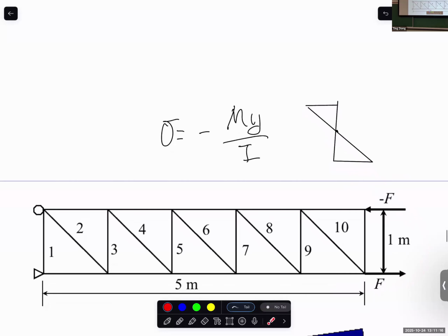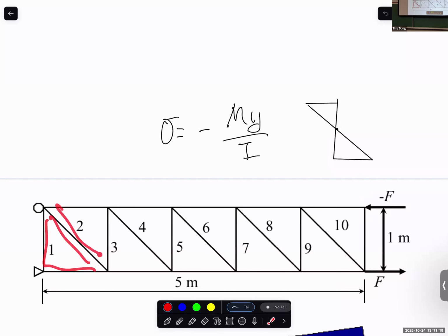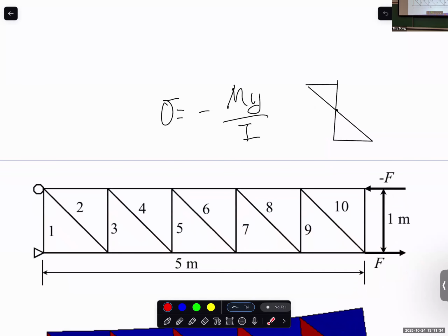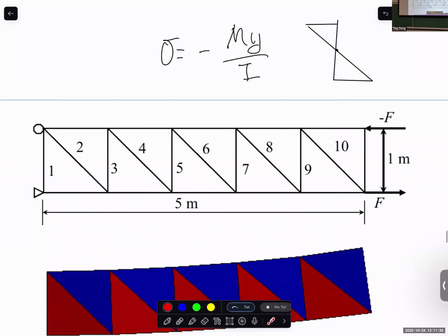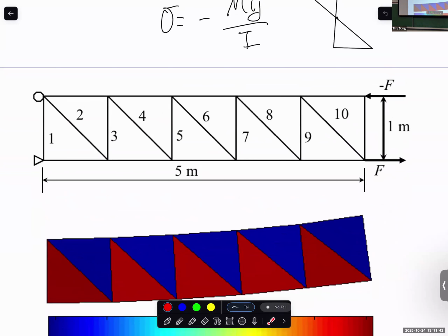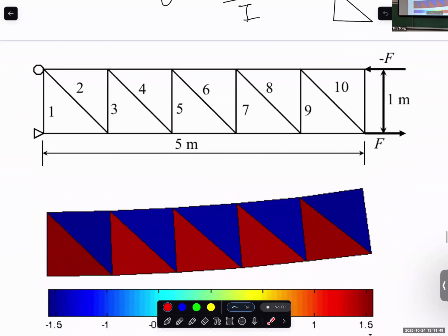But now if we use a CST element, meaning constant strain, or strain and stress in the same order, so a constant strain or constant stress element to model our problem, it can only give an approximation. Make sense or not? I think in tutorial 4, I showed this one. Let's say first we try to use 10 elements. And now you can see that these are different colors. And of course, you probably already know that this is a stress plot.